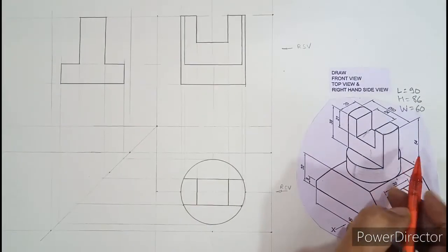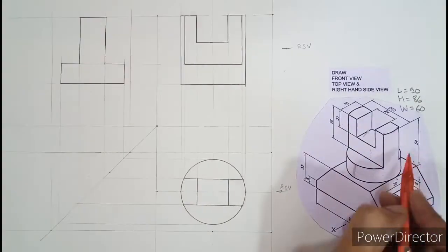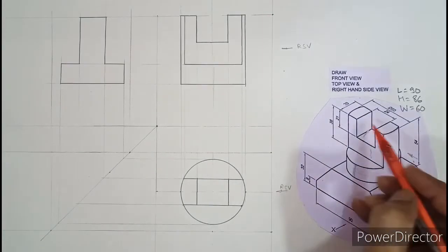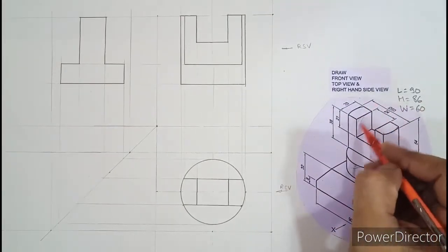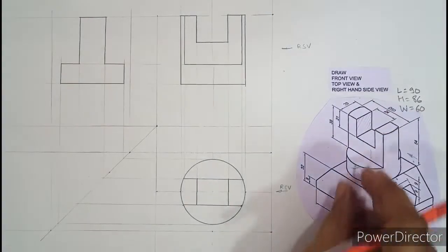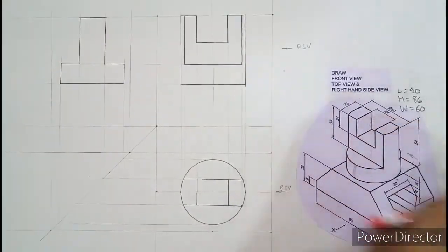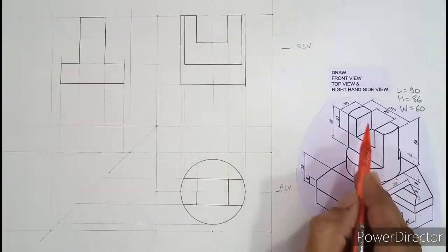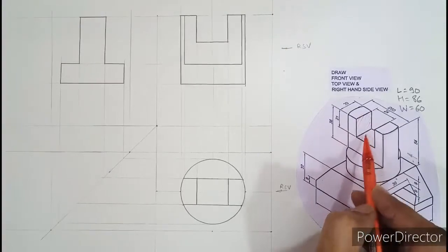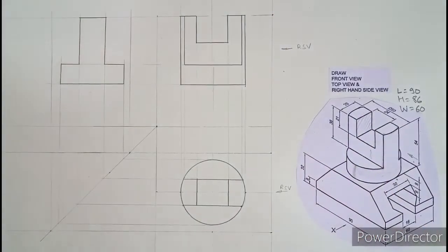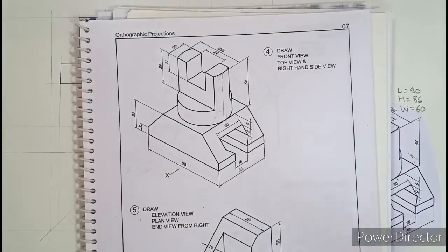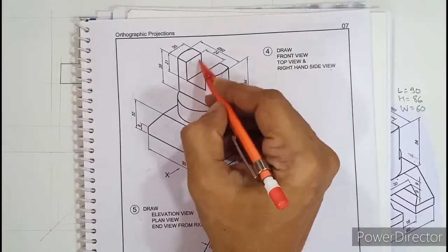The last and very important thing what is left in the side view is, so try to visualize from side. So when you look from this side, you cannot see a cutout. So whenever there is a cutout, you have to quickly understand that hidden lines have to be there. Hidden line is the one where you need to have a good control. So in the side view, there is a cutout or a rectangle like this. Carefully observe this rectangle. Okay, so let me enlarge a bit and look at this one. So you cannot see this surface from the side.